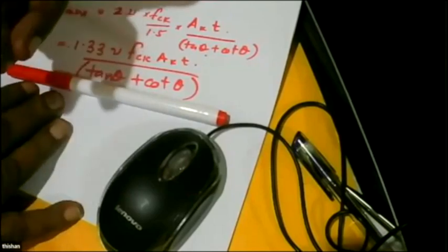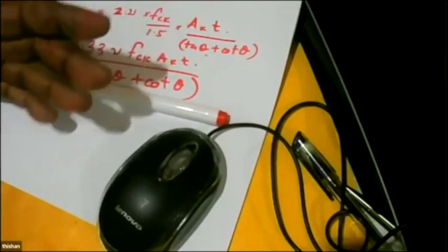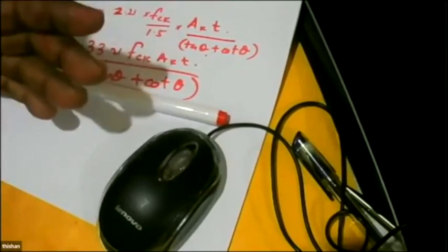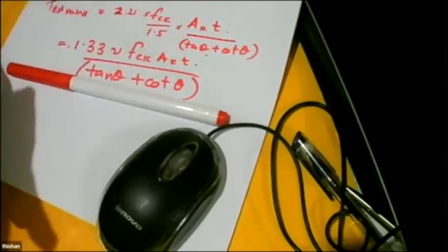Then the procedure is the same as this one. We have to make sure the combined shear and torsion ratio is less than 1. And then design the longitudinal reinforcement and torsional reinforcement in the normal way.